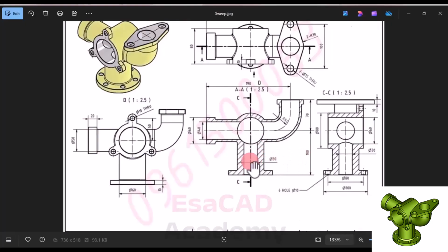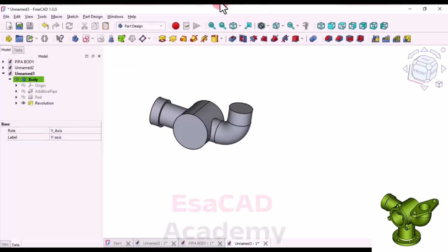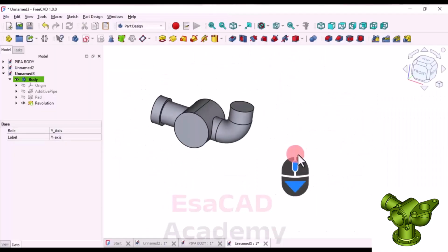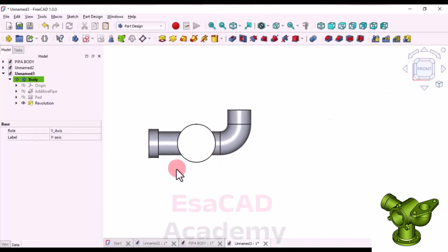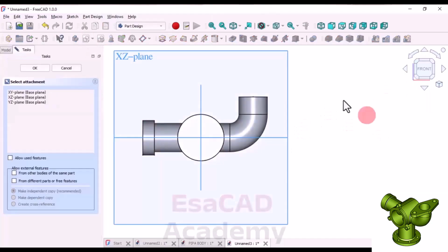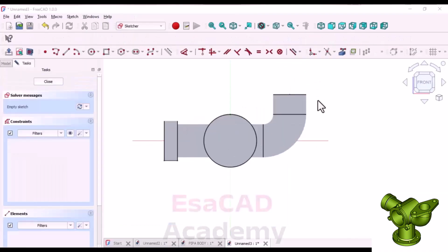Alright, next, we need to set the thickness here to 100, and this value will represent the diameter of the component we're designing. Alright, let's proceed with setting the thickness here to 10 units. Okay, let's get started right away. Tap on the front, stay in sketch mode. Alright, let's go ahead and hide this first.